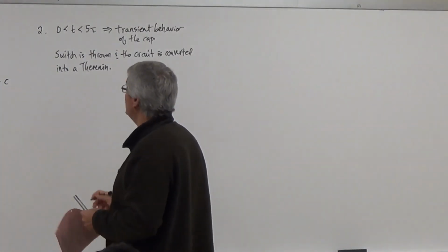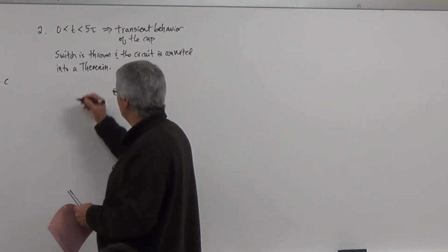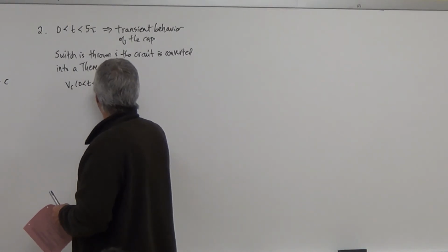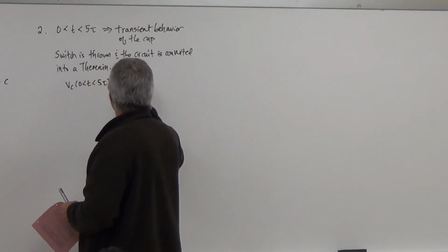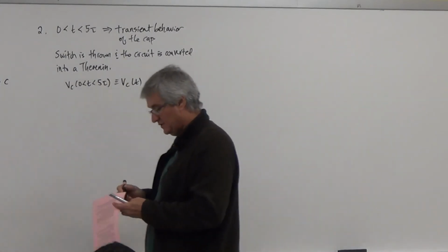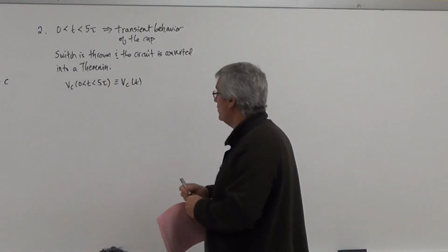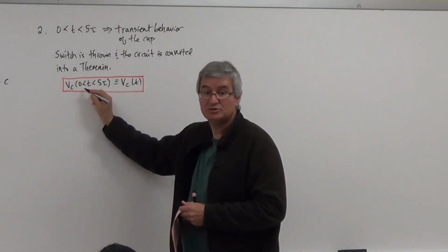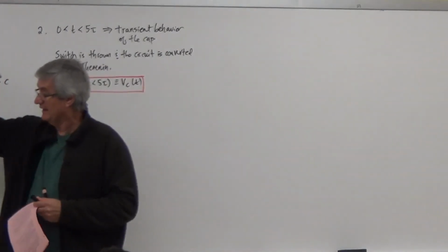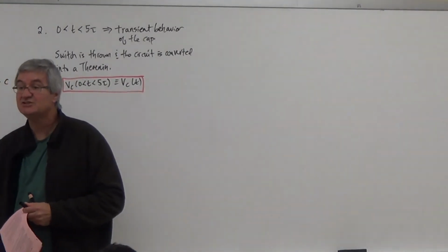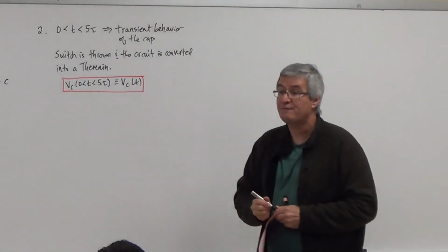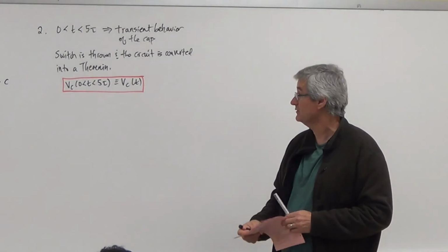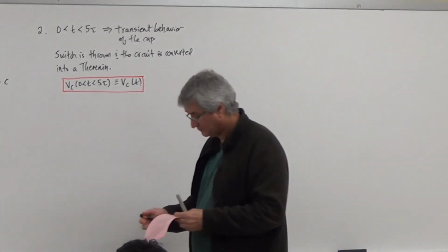So how do we typically write this? When we say that we're in this period, that, by definition, is the voltage of the capacitor as a function of time. This is what we're most interested in. But it turns out that to get this solution, we need this initial condition for the circuit, right? A first-order differential equation requires one constant, and that's the one.